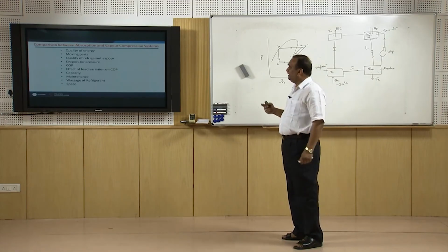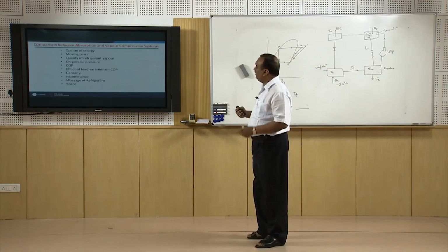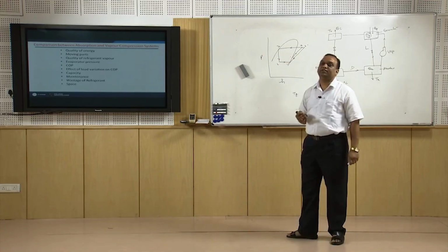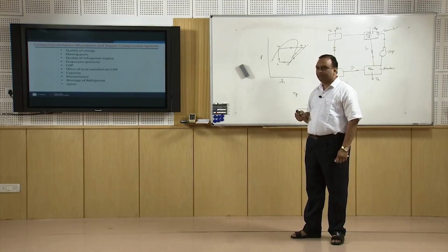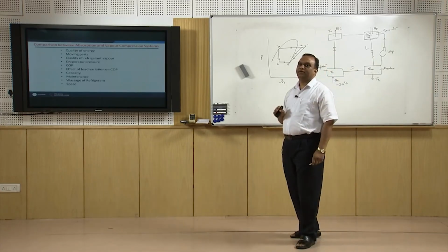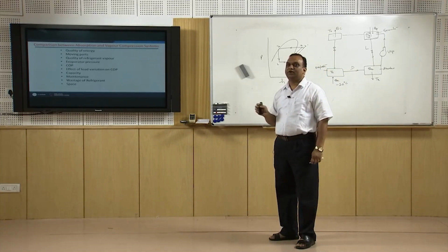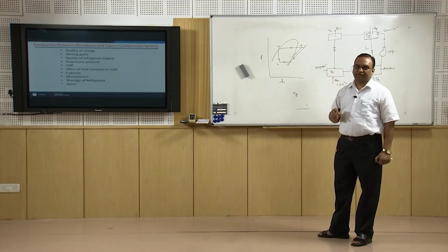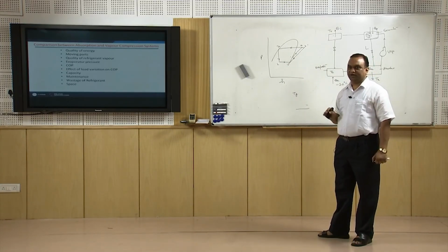There are many more issues which make the vapor absorption system superior to the vapor compression system, especially for high tonnage of cooling. These systems are not economically viable for low capacity systems like 1 ton, 2 ton refrigeration. For those capacities, vapor compression refrigeration systems are recommended.